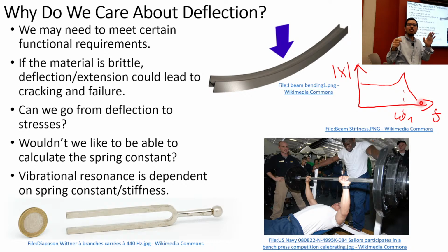But you have a general idea that if you're getting a car that's low to the ground and it's meant to be a roadster, the stiffness is quite high. But if you are going for a vehicle that's going to be on the dirt, and you have lots of bumps and you're going pretty fast, you're going to have lower stiffness in your suspension.